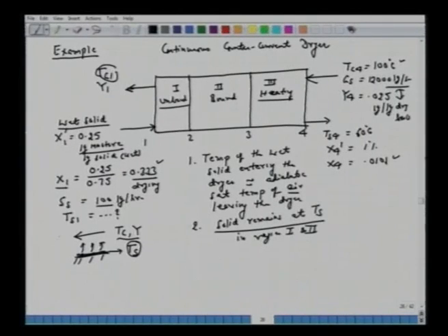All right. So under steady state, we have the surface temperature as adiabatic saturation temperature, or this could be wet bulb temperature. We talked about this. If you neglect the radiation effect or conduction effect, then the surface temperature will be wet bulb temperature. Otherwise, it reaches the adiabatic saturation temperature corresponding to this air quality. So that's very important that we understand here.